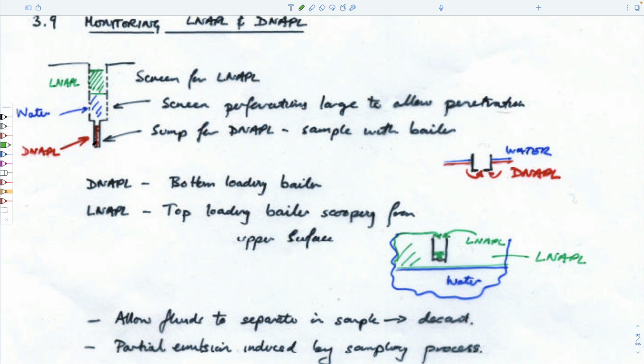If you drill a borehole, and that borehole goes through a pool of LNAPL sitting on the water table, then what it would give you would be this height of NAPL that would sit on top of the water in the borehole, but this wouldn't represent necessarily a true depth. This, in our borehole, as we said earlier, would be height T, uppercase T. And actually we want to be able to determine what W is, right? We just talked about that.